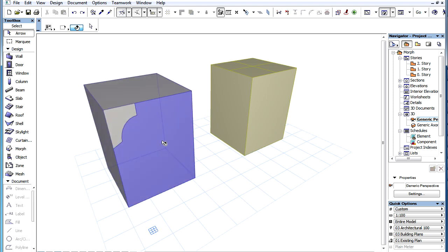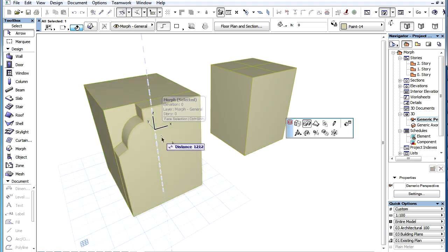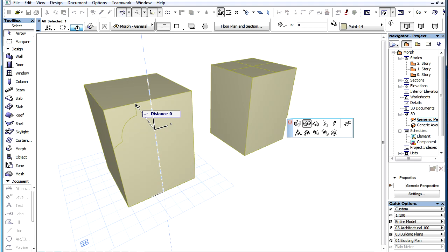If you have two coplanar faces that have a common boundary edge and the starting point of your tube path needs to be on that common boundary edge, for example, this node, there are two methods you can use. The first is to click on the face you wish to tube, activate the Tube command, then click the point on the common boundary edge you wish to be the starting point of the tube operation.